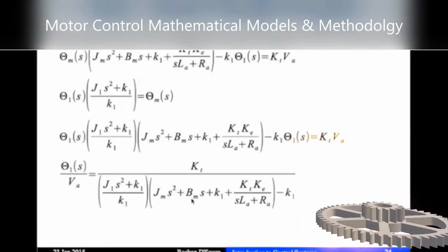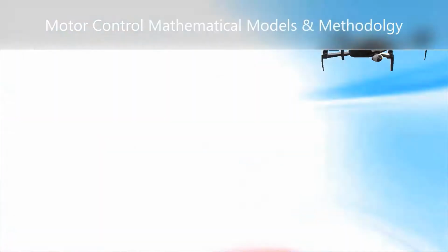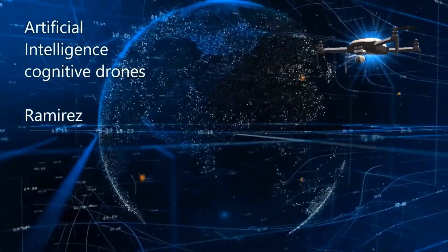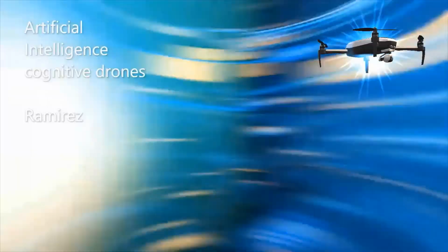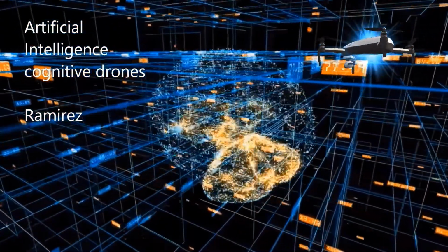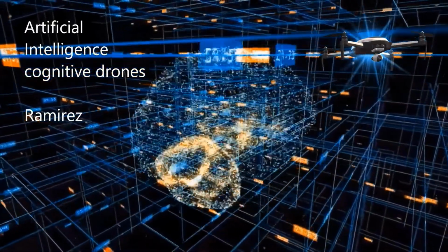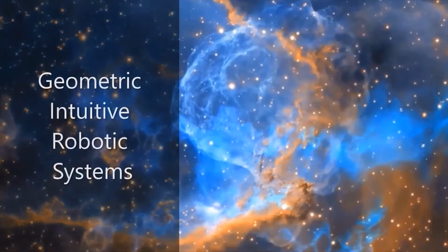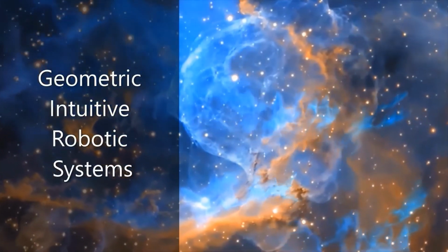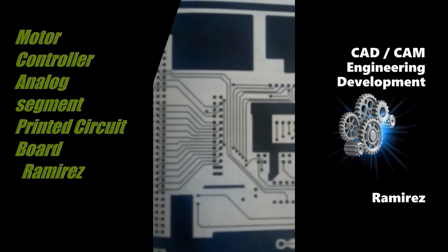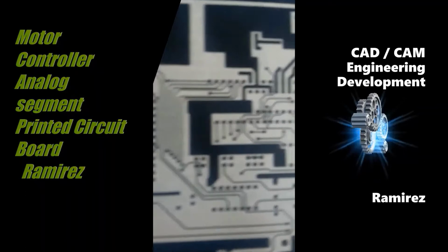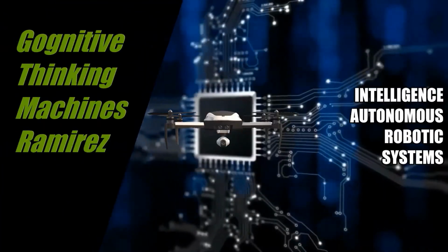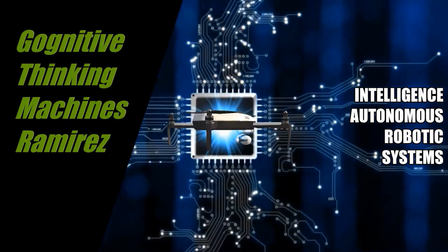The rotor is composed of a group of coils. The rotor coils are sequentially connected to the motor leads through mechanical switches, brushes. The stator magnetic field is generated by a permanent magnet. The torque applied to the rotor is the highest possible because the load angle theta is about 90 degrees. Forcing a current in the motor causes the rotor to generate a magnetic field.